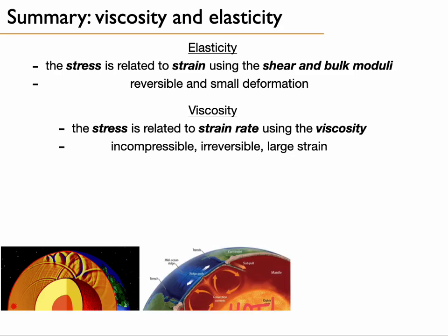The viscosity, it relates the stress to the strain rate. And we have one coefficient, it is the viscosity coefficient. Usually deformations are mostly incompressible in the viscous realm. They are irreversible and they can lead to large strains.